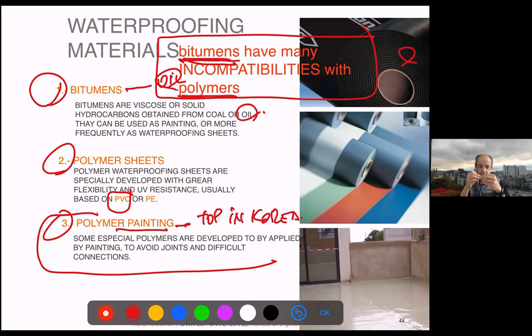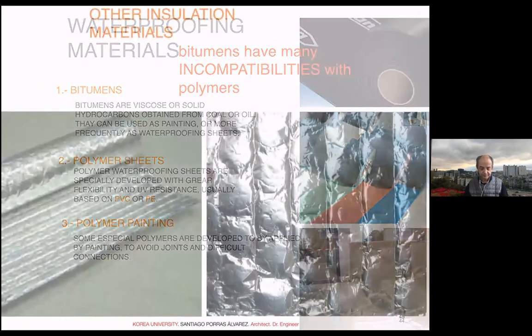They have many ways of being processed, but that may also interact with polymeric insulations such as polystyrene, which is maybe the most used in Korea, the famous isopink, or the styrofoam, right? So in that case, you might want to use a different insulation, like probably fiberglass, or have a separation layer so they don't touch. You will minimize that problem.